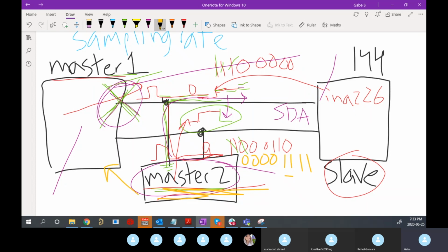But try to understand why I2C is open drain, like Mahmoud asked at the start. Why is it not just push pull? It's mainly for this arbitration reason, so that we have a way to decide who wins, because we only have one line we have to share.